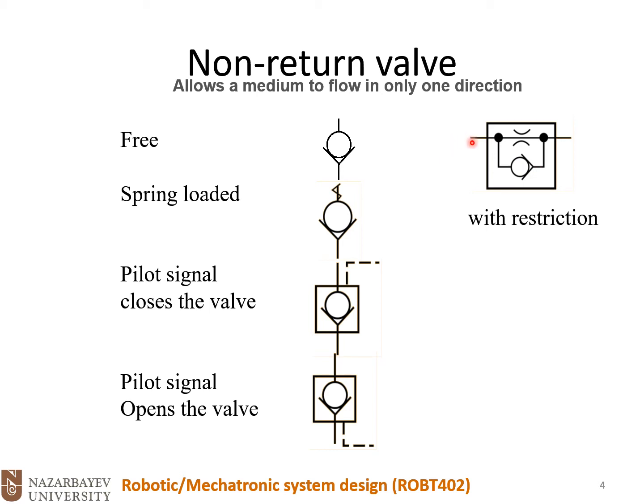Once the air flows from, let's say, left to right, it cannot go through this way because the ball will block the pathway, and it has to go through this throat. Once the air flows from right to left, since we have a resistance here, a big portion of the airflow will go through the non-return valve because the pathway is free, just like a short circuit here.